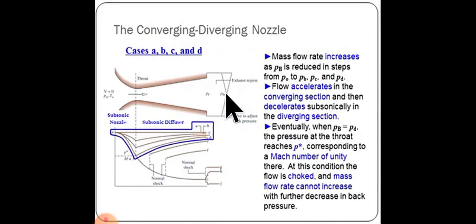So now assume that the supply pressure is fixed, because it's coming from the boiler. We can only open the valve from this point to allow the steam to flow, and further we decrease the discharge pressure by converting this steam into water, because when the steam converts into water, it contracts. So the volume decreases, so the pressure over here will decrease. The more the pressure decreases over here, the more velocity of the steam will be produced, and the more steam will pass through this channel.